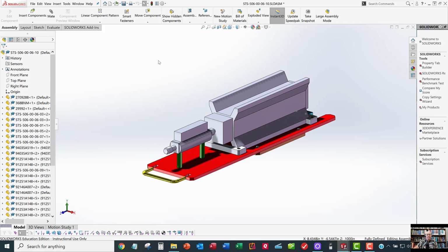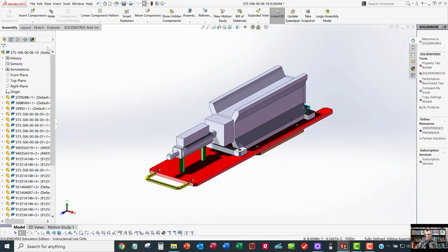We don't have to do it like Inventor. In Inventor, you create a presentation file that's separate from the assembly model, and you have to keep track of the two files, and it's a pain in the neck. So SolidWorks lets you do everything in one assembly model, and the way we locate the exploded view or the configurations is by going to the Configuration Manager. And that's this third tab over at the top.